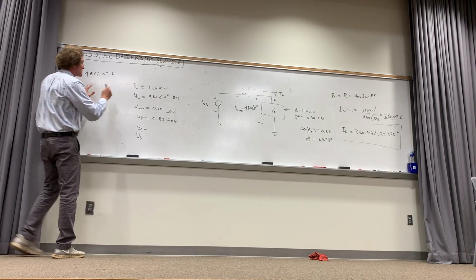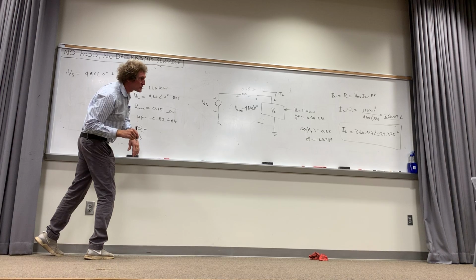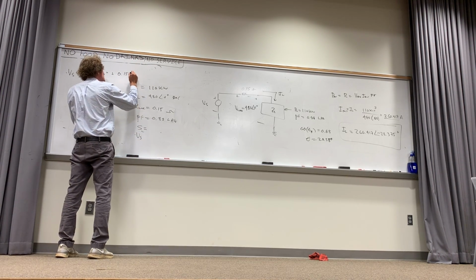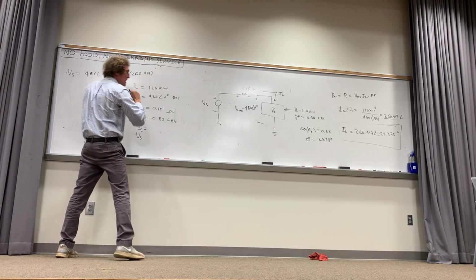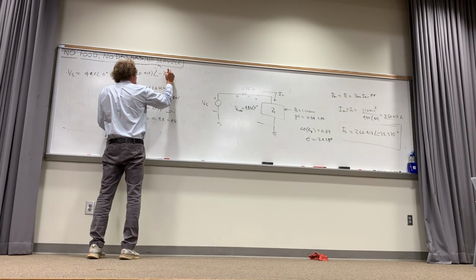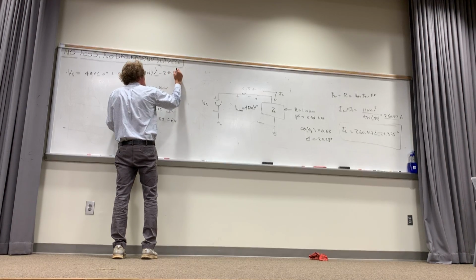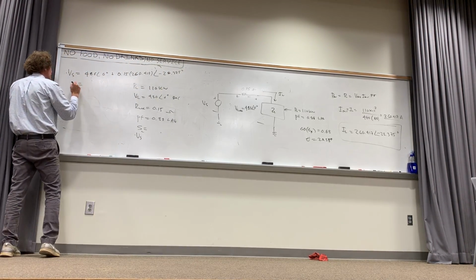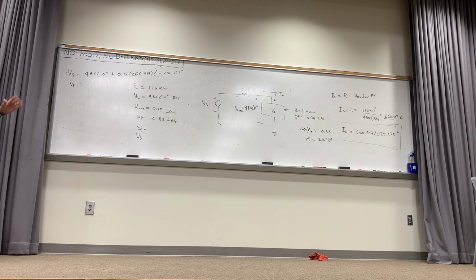So now it's going to be 0.15 times the line current, which is 260.417 at an angle of minus 28.375. And you can give me VS. Somebody can. You're adding polar numbers.